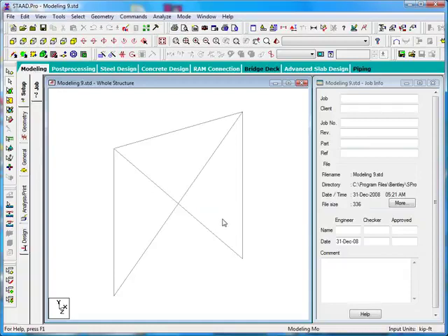And what we'll do here is turn on node numbers with Shift and N on the keyboard. I'll also turn on node points with Shift and K so we can see a little more clearly where those node dots appear. Let's just assume that in this case what we want to do is create a 2.5 foot long cantilever, a horizontal cantilever, to the left side of this node number 6. So one convenient way to do that would be to copy and paste node number 6 2.5 feet to the left, and then just draw a member between those two nodes.